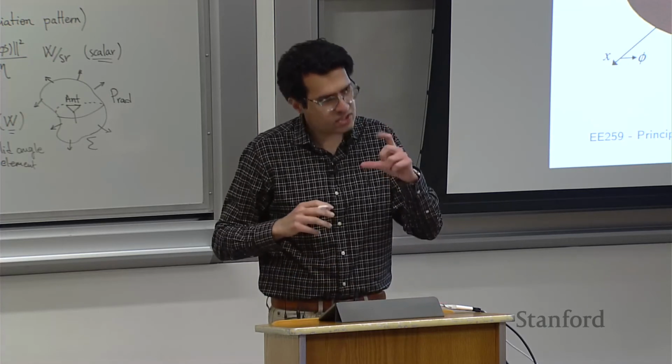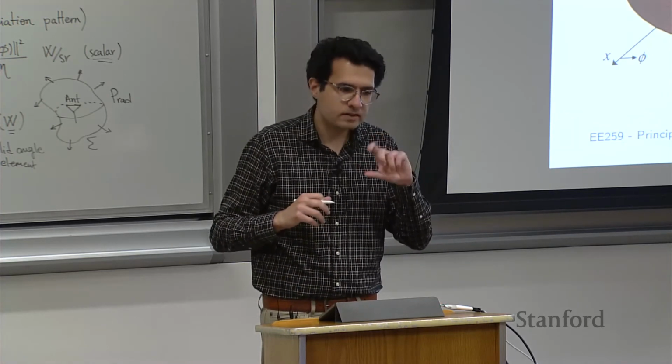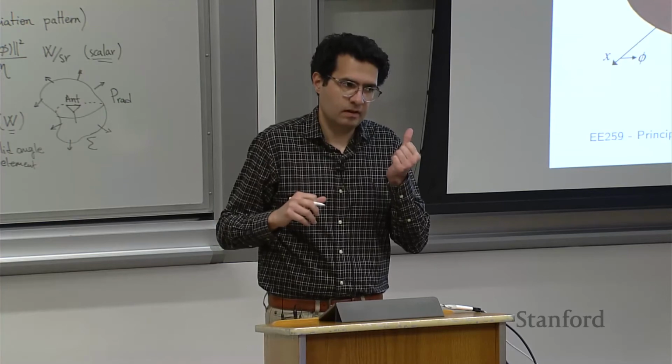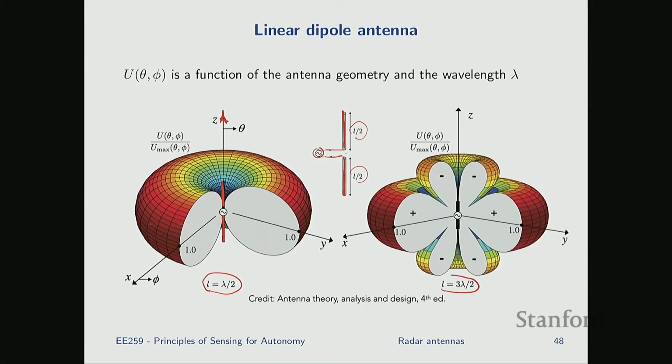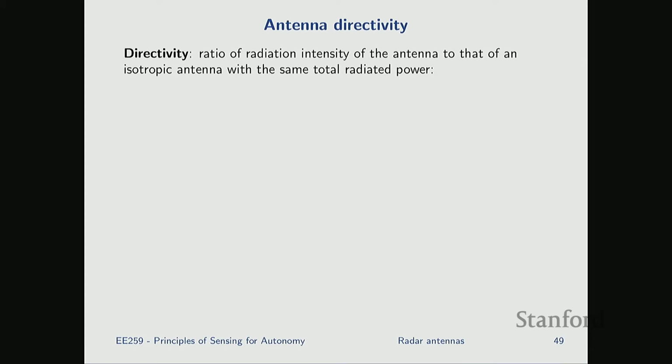And now if you change the length of the antenna, or alternatively, if you change the wavelength of the signal that you're feeding it, the lambda, such that L equals 1/2 lambda, 3 λ/2, the radiation pattern completely changes. Now you still have your main lobe kind of like around this, but now you add this side lobe also. So geometry, the shape of the antenna, and also the dimension of the antenna with respect to the wavelength, those two together determine the radiation pattern.